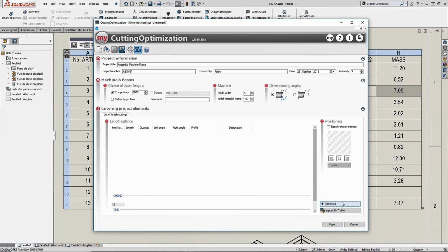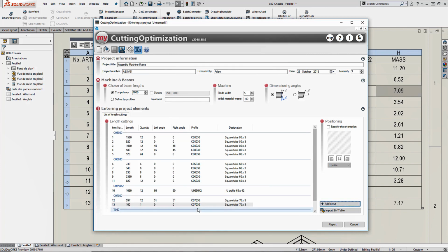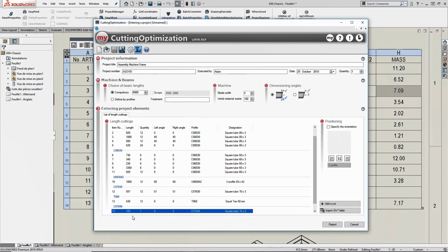If we require additional lengths inside of our cut list that aren't actually in our project, we can go ahead and select those. We can add in the length of item that's to be used, and also the quantity of items can be increased. So in a case where we don't necessarily have that in our project in SOLIDWORKS, it can easily be added.